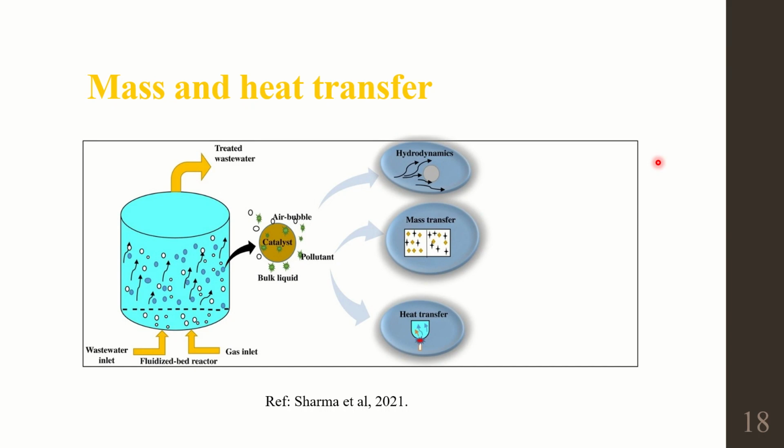So it becomes necessary that we understand what is happening inside the fluidized beds in terms of mass transfer and heat transfer. Already we saw why we prefer fluidized beds: in packed beds the chance of hotspot formation would be there, and in fluidized beds the temperature is evenly distributed.